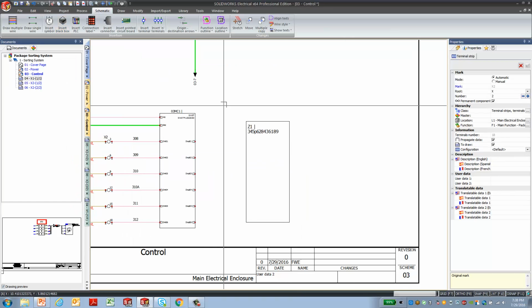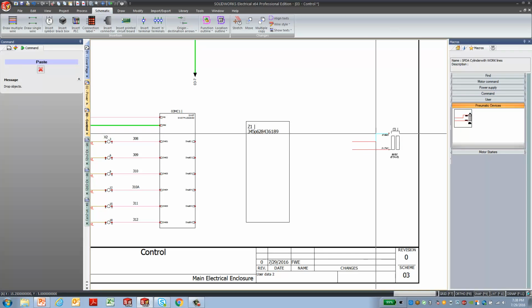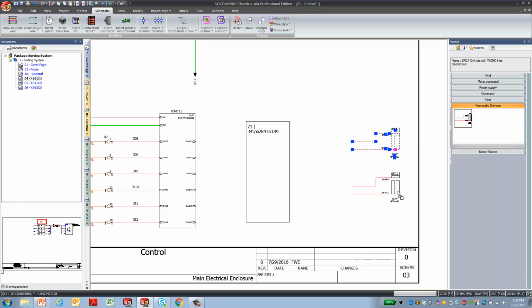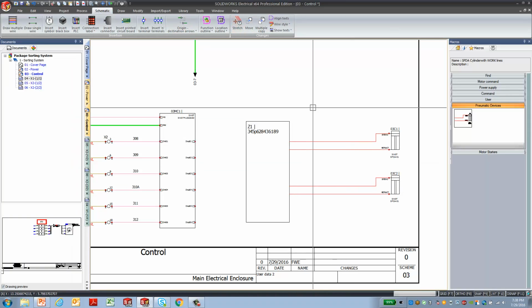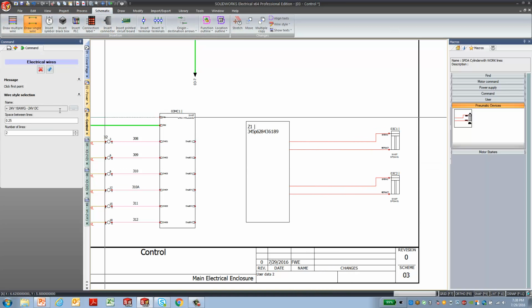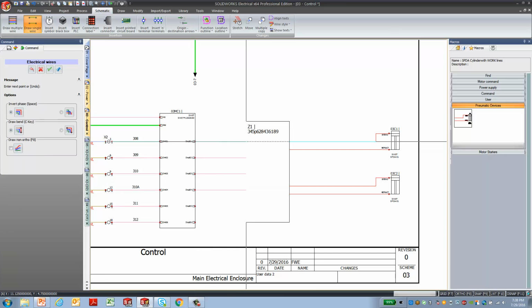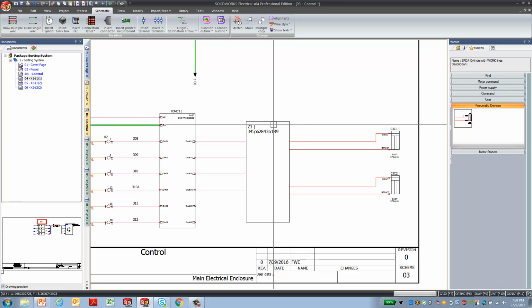So there's my part number. And let's go ahead and add those hydraulic or pneumatic devices. So we'll place one here. Just control drag, make another one here. And then we'll stretch these hoses out. And let's go ahead and use our control wires. Looks like we're at a larger spacing, so we'll use 1/2 inch, and we want 4 of them. And we'll just go to the 4 inputs. Okay, so it's almost there.